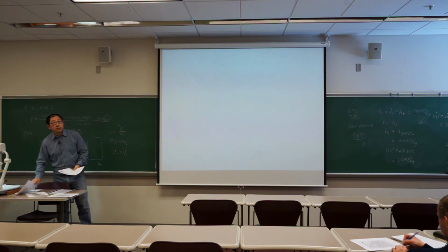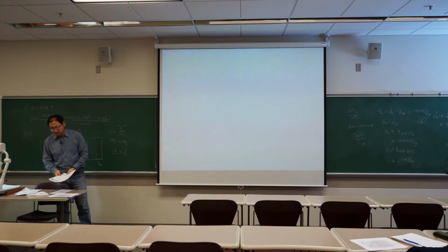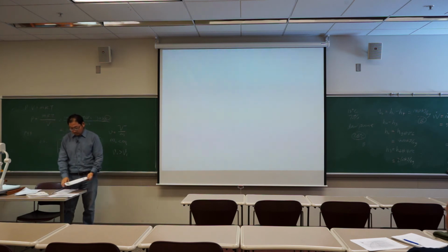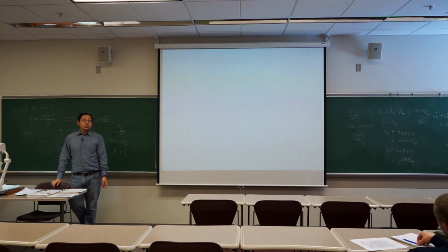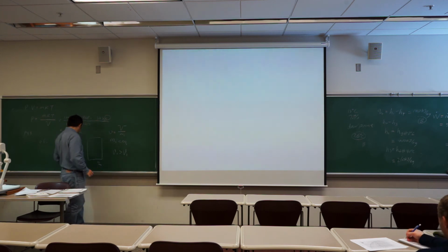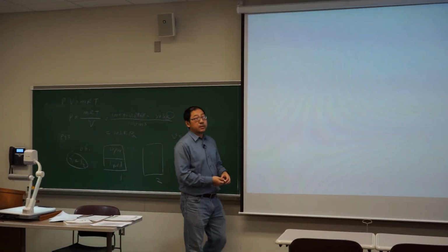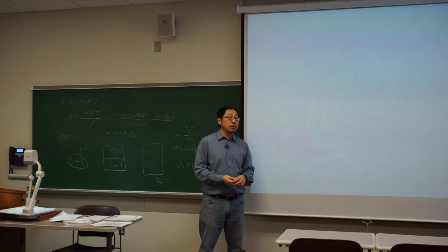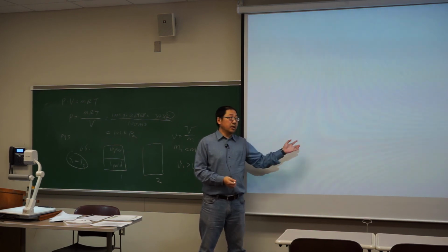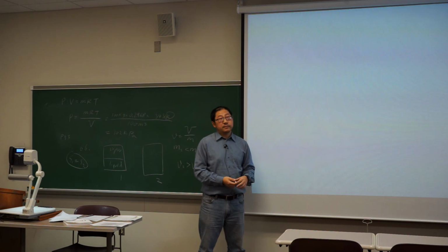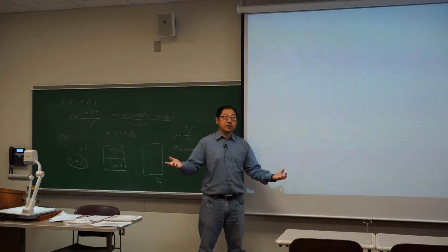Are there any definitions or words that automatically go together? So like isentropic means this. Isentropic just means the entropy does not change. So S1 equals S2, entropy remains constant, isentropic. And the other one, insulated, means there's no heat. And then constant temperature is isothermal, temperature remains constant.